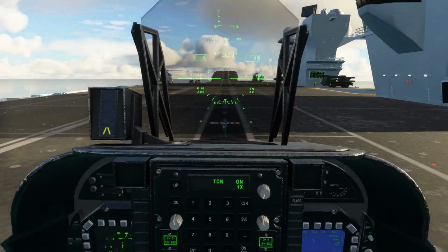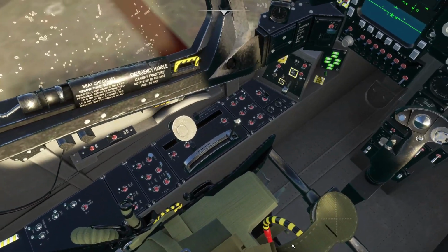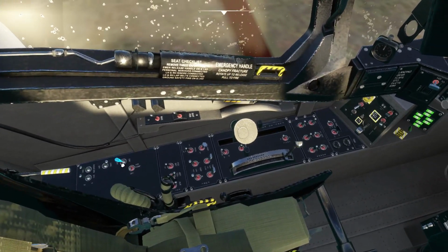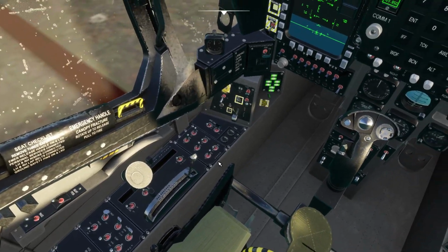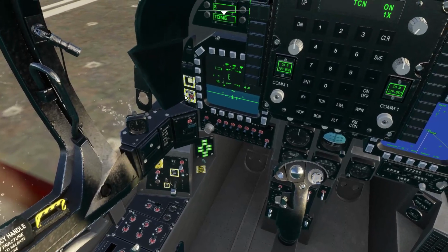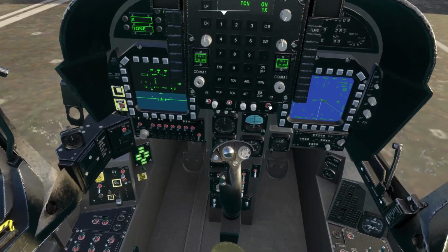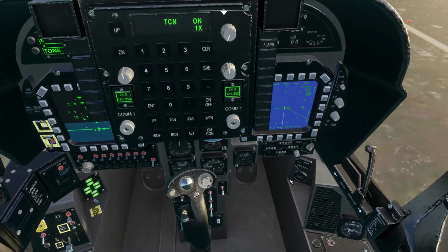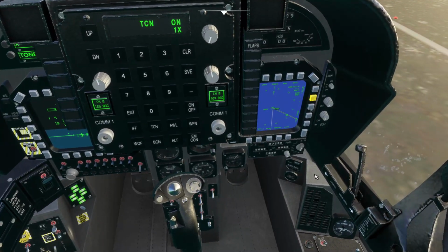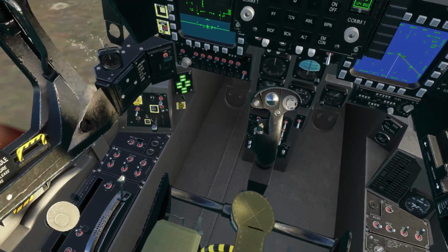Right, so I thought I'd start on the deck hot and save the startup process. I'm just going to go do the final checks for takeoff. Oxygen on, flaps down to stall. We're going to put the HUD master mode to V-stall. Radar altimeter will be in use for this mission. We're going to set waypoint to waypoint 1. Okay, we're all good to go.